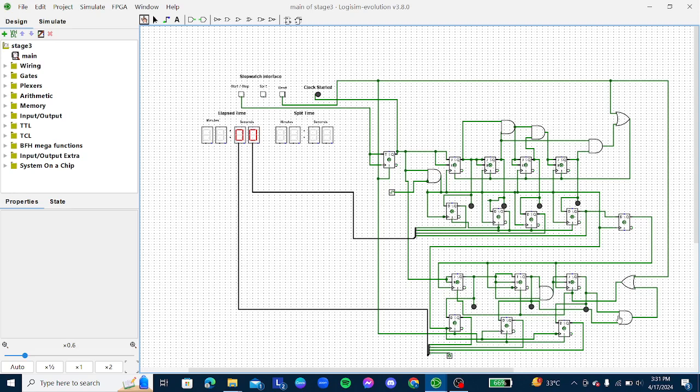I used D flip-flops, and with the output to make sure that the counter never displays more than 5 in all the counters. All the D flip-flops' clock inputs are connected to the clock directly.